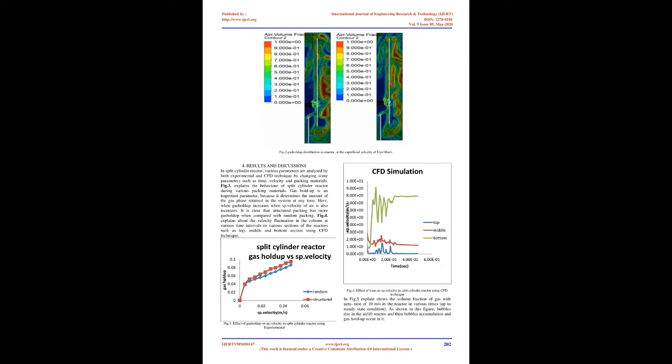The experimental setup consists of a cylindrical acrylic column of 150 mm diameter and height of 1000 mm. The column is separated into two sections, riser and downcomer zone, by using a vertical baffle, and their separation ratio is 1:1. The baffle is placed at a clearance of 0.2 m from the base of the column. The sparger is placed at the bottom of the riser side, 3 mm and 5 mm.